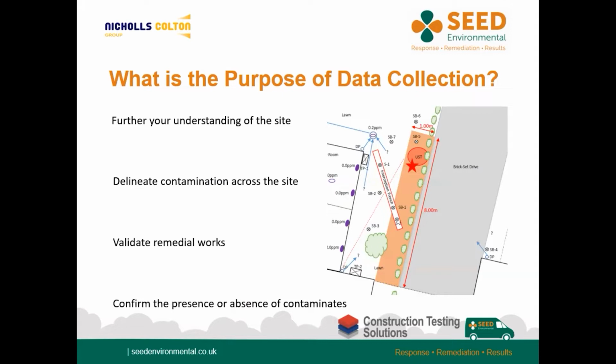This could be to log the geological profile and identify resting groundwater levels to confirm if a migration pathway identified within your initial conceptual site model was present and therefore still of concern. Or you could be looking to confirm if specific contaminants are present at the site, and if so, how far they have migrated vertically and or horizontally through the unsaturated material.